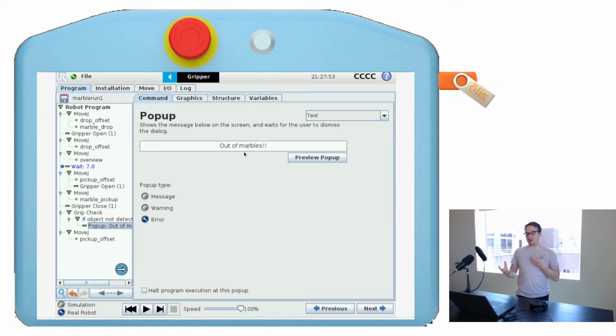So what we want to be able to do is to do this remotely from wherever we are. And you could potentially do remote desktop into the robot controller like I'm doing here, just to show you this on your screen. But you don't really want to restart a robot unless you have video feeds at the same time that are real time and low latency. So you actually know that it's safe, make sure that nothing unexpected has happened, make sure that you can really just go ahead and press play again.